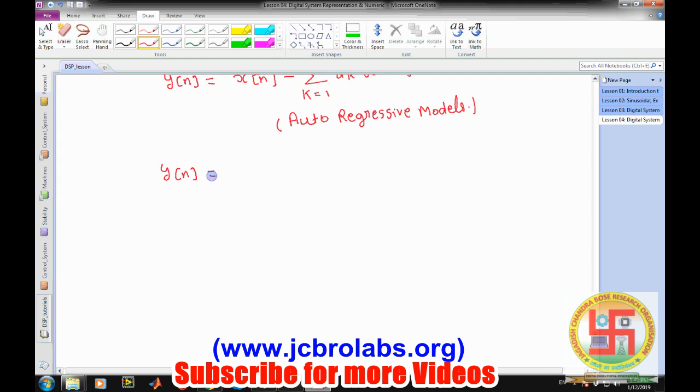Similarly, it could be that our output depends on the present input, past inputs and the past outputs as well. That means a combination of the previous three. So let's say for k equals 0 to M, p of k into x of n minus k, and then minus the summation of k equals 1 to capital N of d of k into y of n minus k.